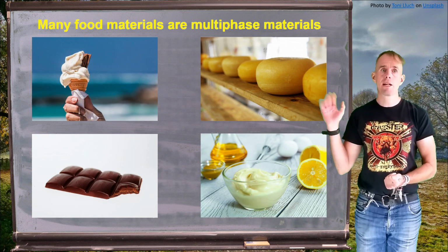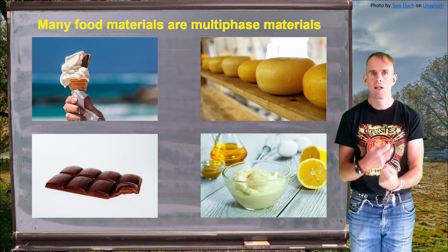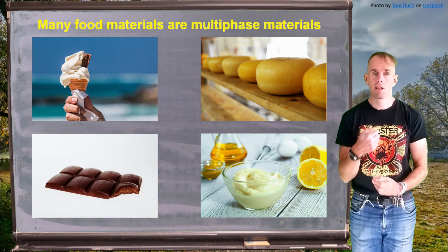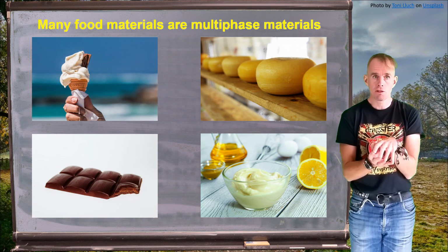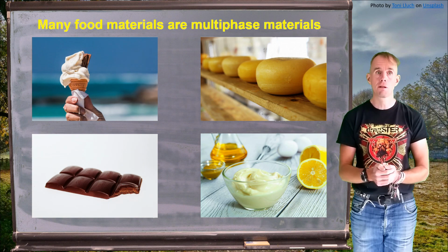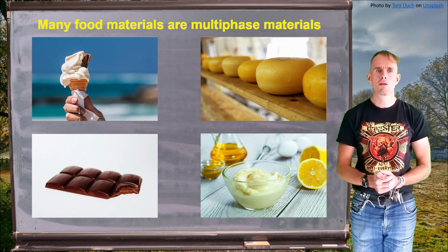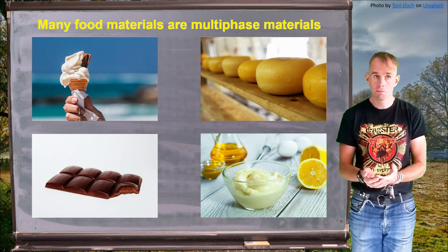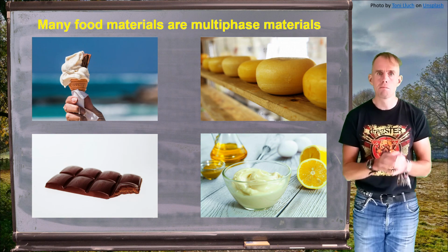Finally, we have things like mayonnaise. Now, mayonnaise is a very good example of an emulsion where we have droplets of fat in a matrix liquid. And so we have, for example, fat in egg white, and that gives us the plastic properties that we see in a mayonnaise. And the shape of the mayonnaise in the bowl there is a very good example of that. So, the key point of putting this slide up is to show you that many common materials that you know about have complex rheologies, but those complex rheologies are driven by the fact that the material is itself multiphase in nature.